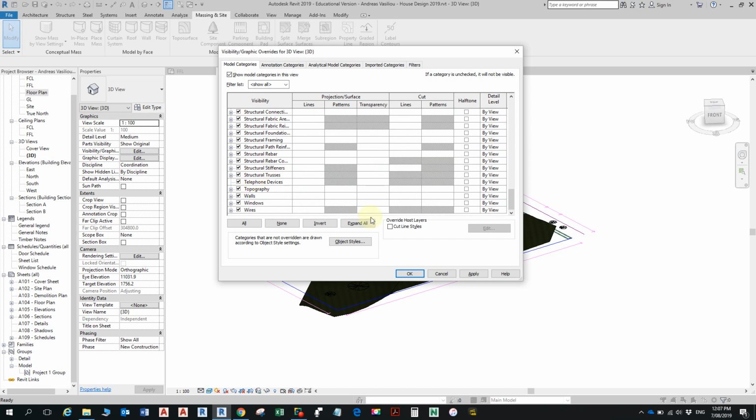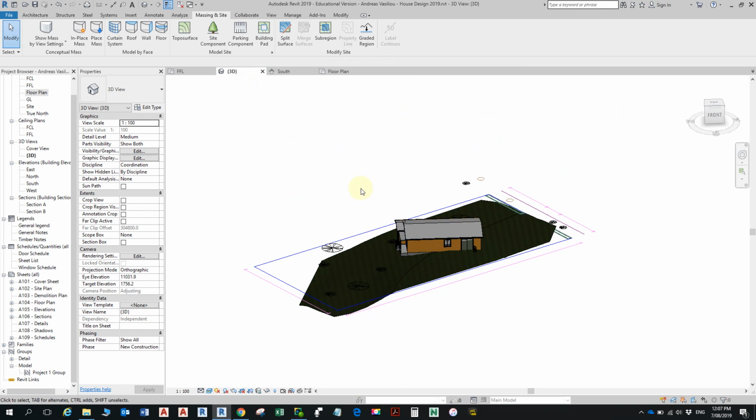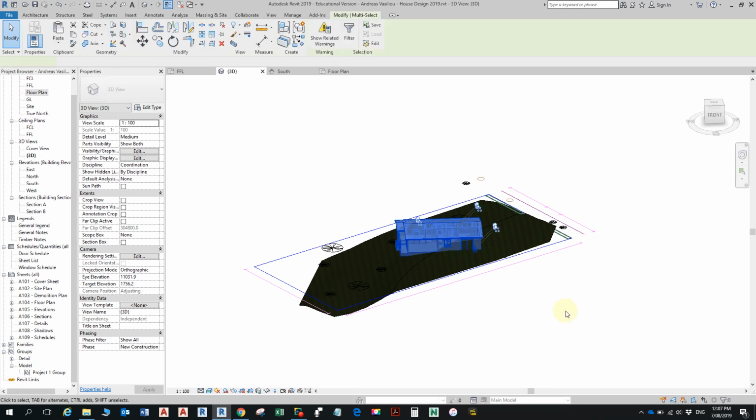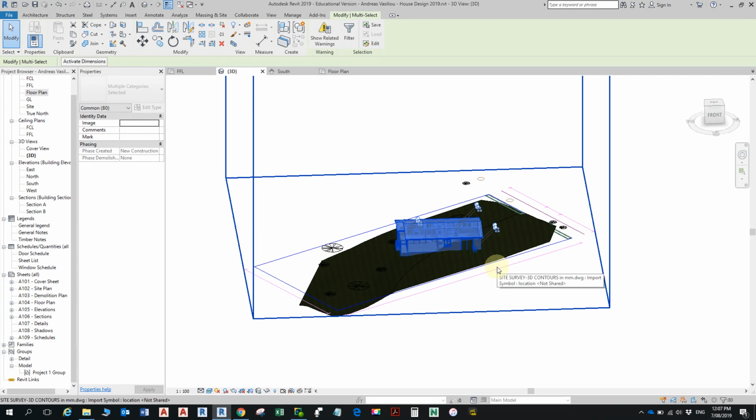And that's all that's turned off, so that's okay. We'll go okay. So what I want to do is rotate it 180 degrees, we said. So what I'm going to do is just do a window over this, like this. Make sure I'm getting everything to do with the house. There are some little pins that are pinned to some other things, but I think as long as those other things are rotated at the same time, I don't think the pinning is a problem.